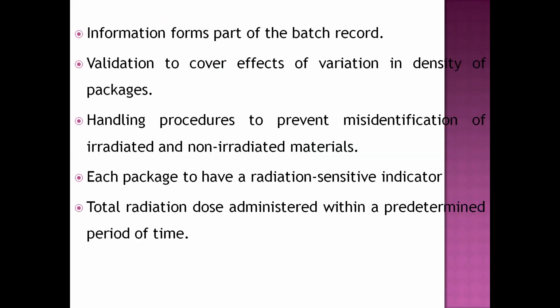then information forms, the part of the batch should be recorded, then validation to cover effects of variation in density of packages, and handling procedures to prevent misidentification of irradiated and non-irradiated materials. Sometimes we forget which one has undergone sterilization under radiation. Each package to have a radiation sensitive indicator in every packet. Total radiation dose administered within a predetermined period of time.